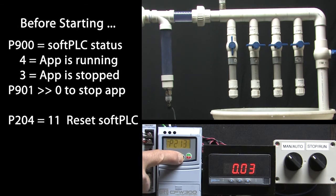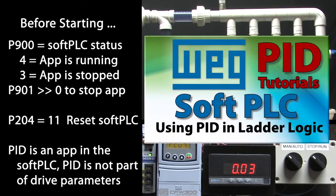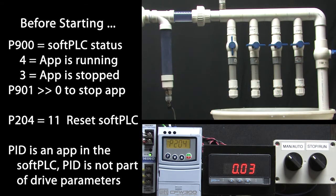Now we can go to parameter 204 and set it to an 11 to reset all of the soft PLC parameters. The default soft PLC app is the PID function a drive uses. PID isn't actually in the drive, it's in the soft PLC. We'll talk more about that in the soft PLC PID video.